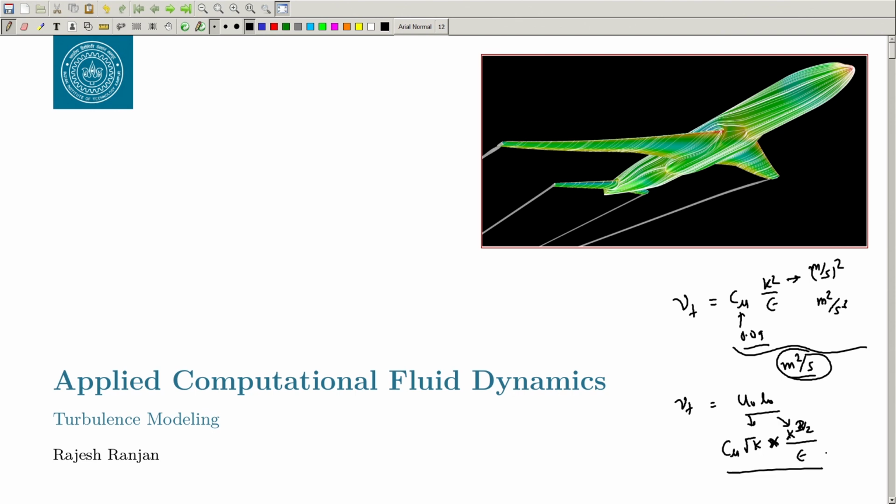Okay. And we saw that this K epsilon turbulence model does not do very well very close to the wall, right. So, we discussed the low Reynolds number model also, and we saw that very close to the wall you need to do some special things, use some kind of damping to get the behavior right.